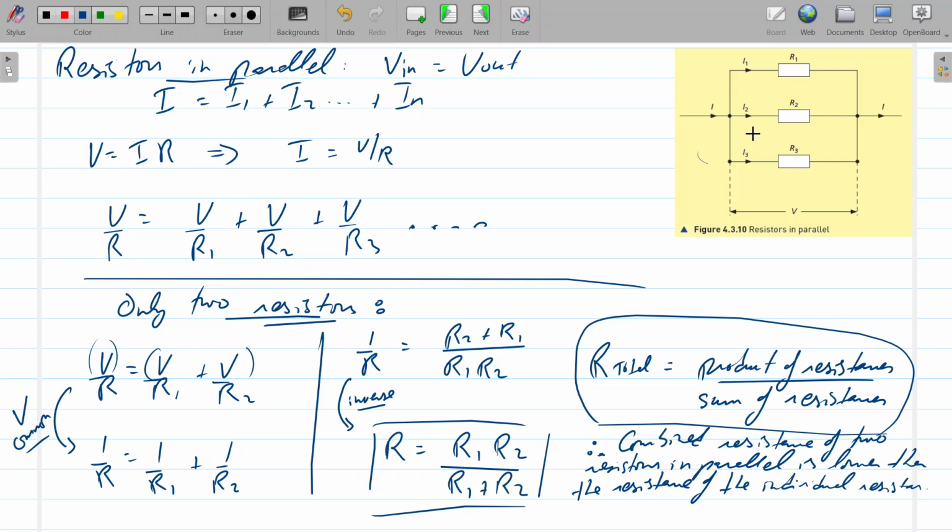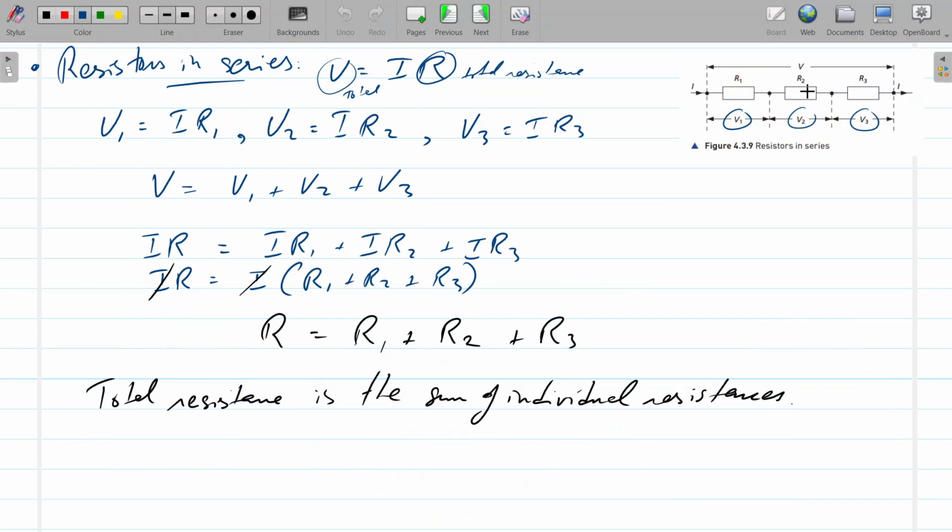Because the current is being split, the voltage is the same, and so it's not going to affect the other resistors in the circuit. Whereas over here, if resistor 2 stopped working, the circuit will stop working because the current will stop flowing through the whole thing. Worst case scenario, it will only work up till resistor 1 perhaps, and resistor 2 and resistor 3 won't work. So it's going to affect the components that come later on, but otherwise, it's going to cause your circuit to shut down.